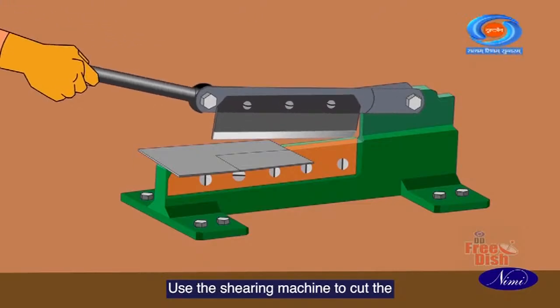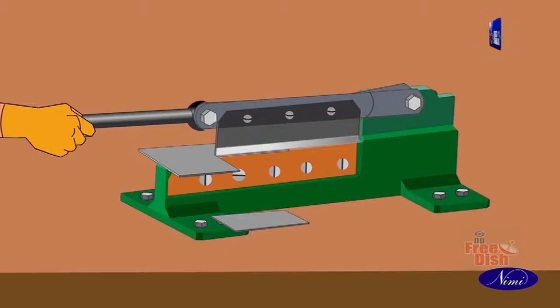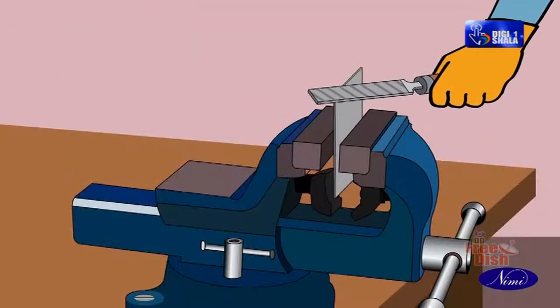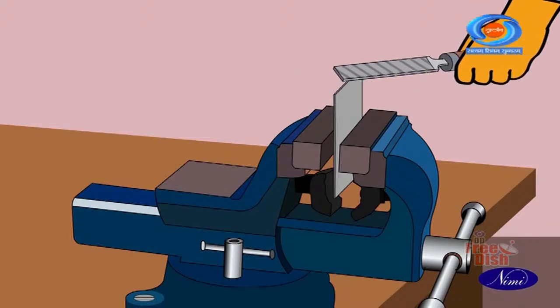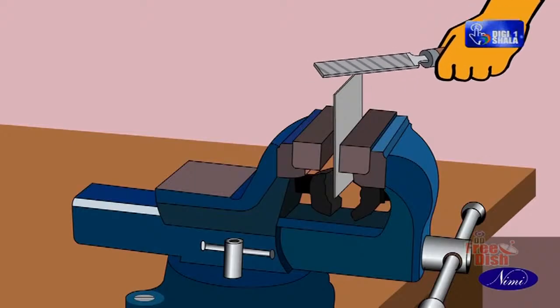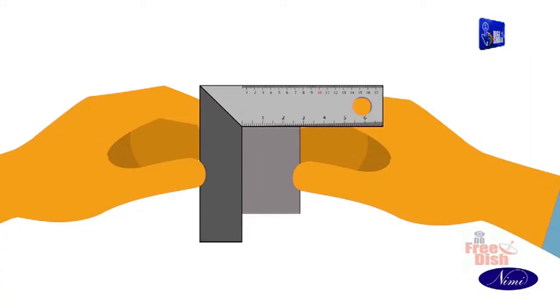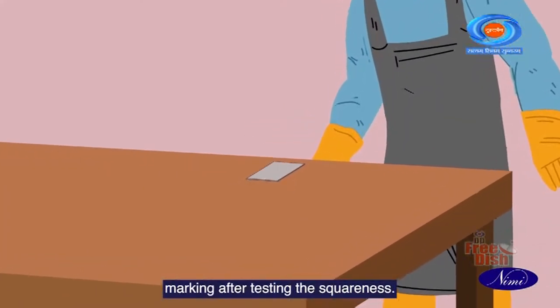Use the shearing machine to cut the job piece according to the marked size. Check the edges for smoothness. Make the square edges by filing. Check the squareness using tri-square. Keep the job prepared for punching and marking after testing the squareness.